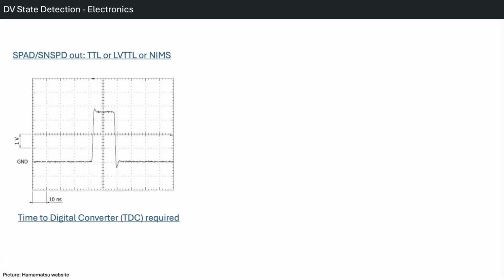I mean the time behavior, time tagging, what we call. What I mean by this? When you detect a photon, for example, you have a circuit. When you detect this rising behavior from here, you just assign an integer for this rising behavior. And if you see another rising behavior, you assign another integer for this, which now your time signal, digital signal is converted to time. Then you can do some correlations and calculate the G2 function, etc.